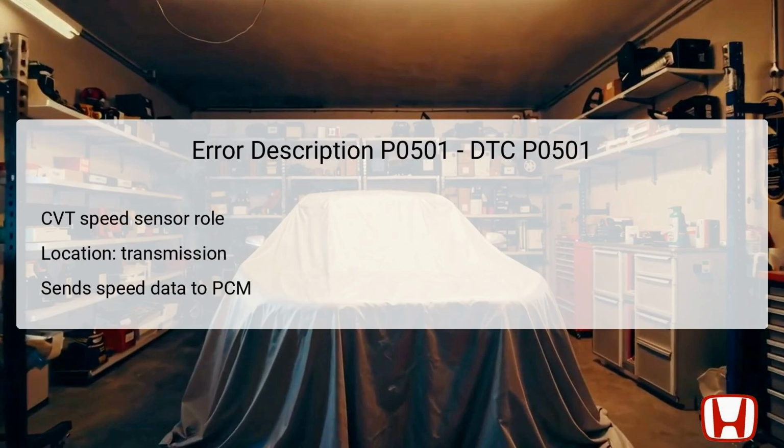The CVT speed sensor plays a vital role in measuring the vehicle's transmission speed. Located within the transmission assembly, it actively converts the speed of the input shaft into electrical signals. These signals are sent to the Powertrain Control Module, PCM, enabling it to adjust various engine parameters according to the transmission's performance. This component is essential for maintaining vehicle dynamics, fuel efficiency, and optimizing shift points.